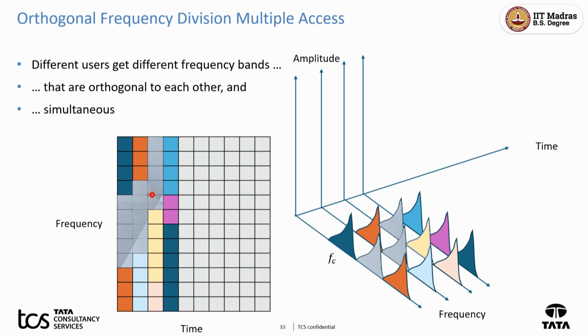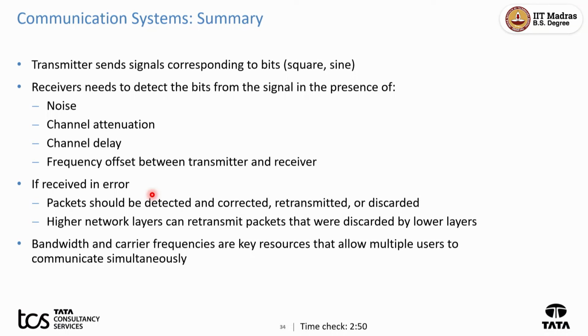If it is a voice call, for example, they will not give you much frequency. Voice does not require so much bandwidth, but it requires regular bandwidth, regular chance to speak. Your signal should go every 20 milliseconds, otherwise you will feel the other person is not there. That is what the QoS is. QCI 1 will ensure you get a chance every 20 milliseconds, but not for so much data rate, just that much. The lowest possible is assigned. In fact, when we run only VoLTE calls, nothing will get used in terms of bandwidth, but it will keep getting used periodically. When we run a 10 GB file download or something, all the bandwidth will get used.